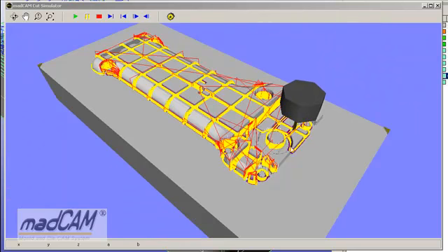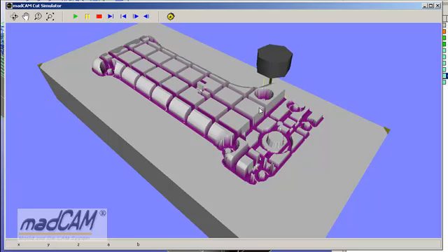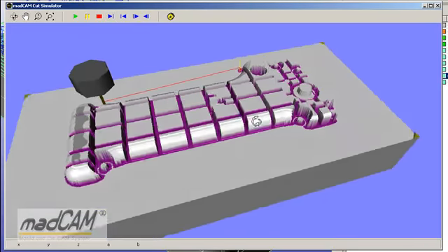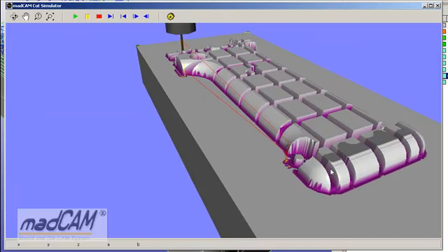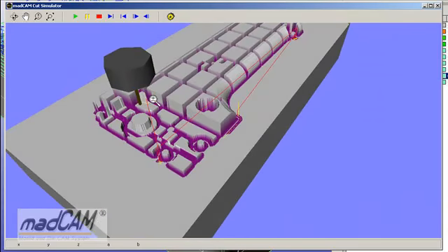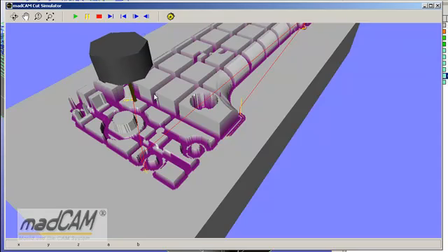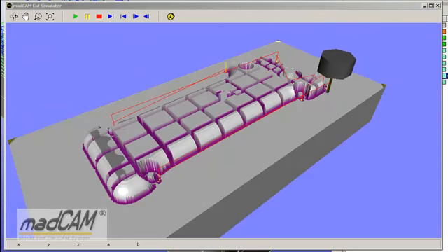And here we can see it goes climb cut in Z levels for keeping the cutting depth constant. And here we see the contour planar remachining, and it will clean up all the relatively flat areas where the previous cutter couldn't reach material. Speed it up a little bit.